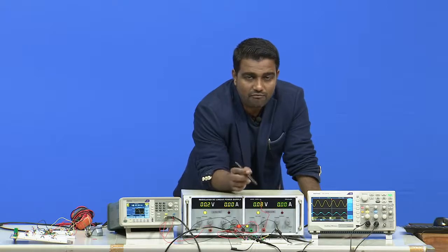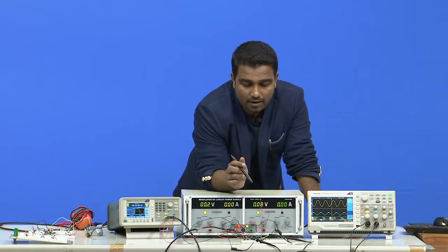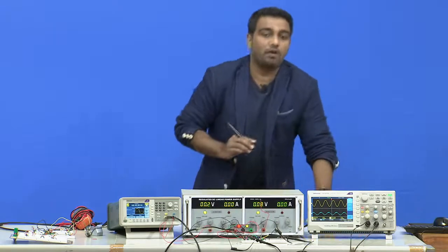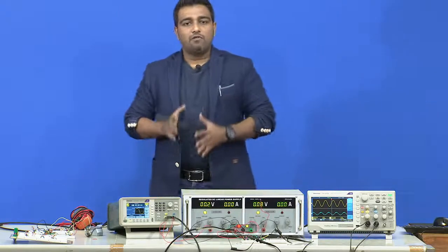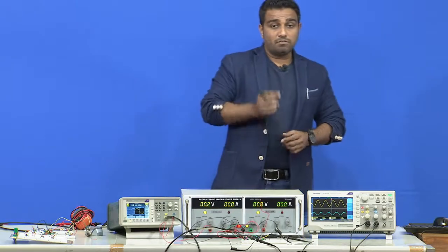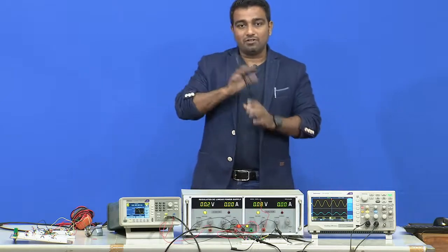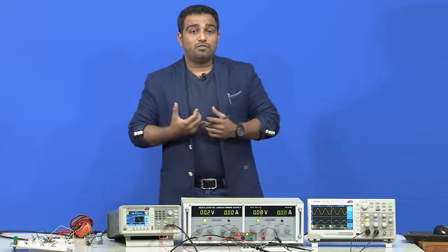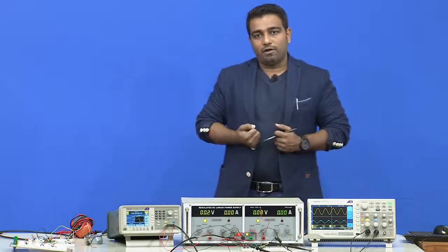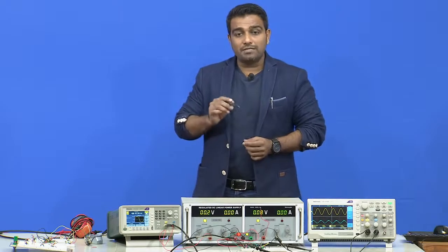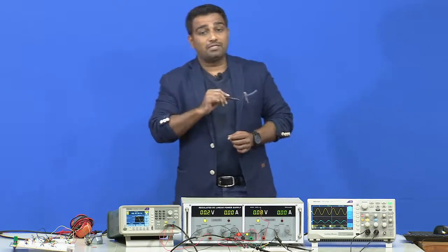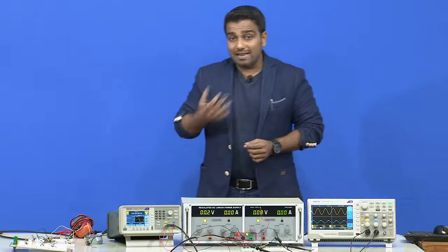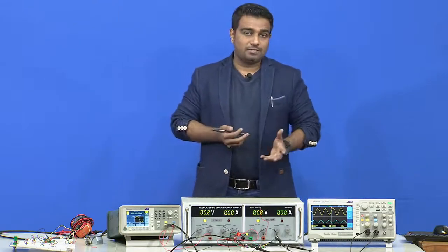So, the point was why we were not able to see it, so we have identified the mistake in the circuit design, and what we found is one of the terminals was not properly grounded. Alright, one of the terminals of the summing amplifier was not properly grounded. Just because of this small error, which is not really small, you cannot find the output which you are looking for. But the point is, you should be able to rectify your mistake, you should be able to find out where exactly the fault is, right.